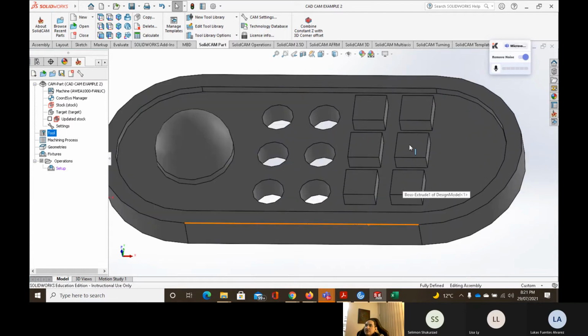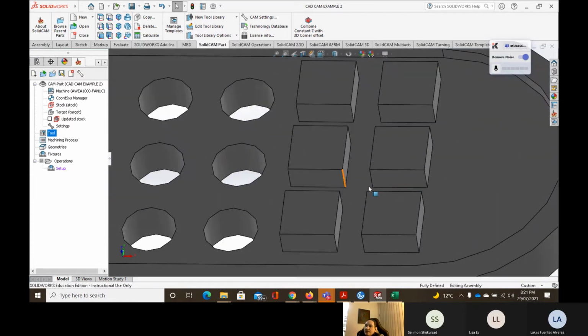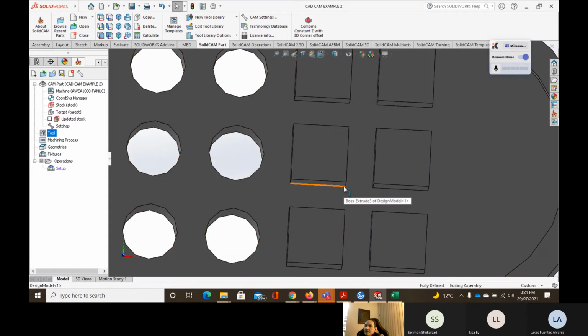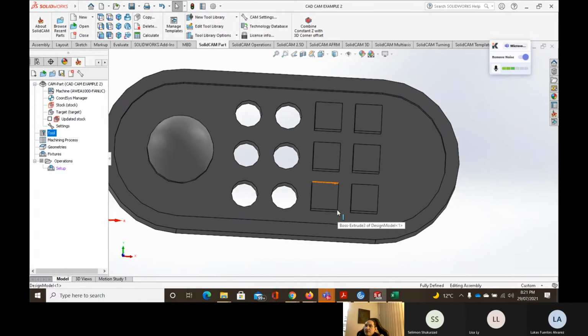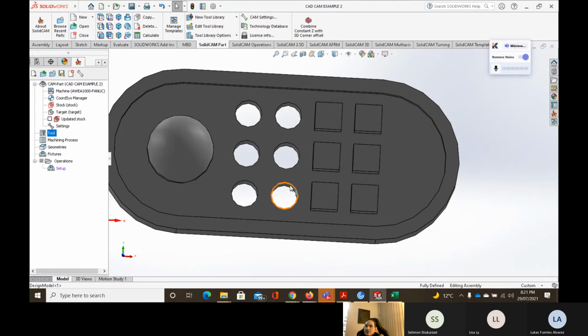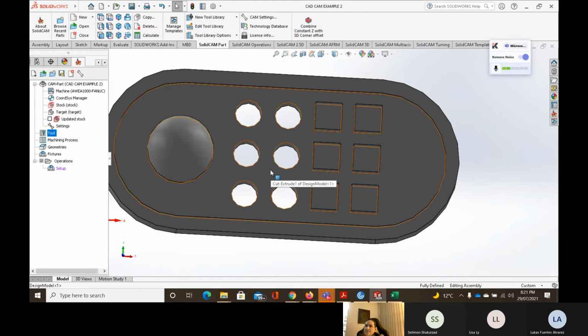To select the tools, we need to pass the tool form here between these cubes. The distance from this line to that line is 10 millimeters. I'm going to choose the cutting tool to be an 8 flathead. I'm going to do drilling for these holes, 20 millimeters. I'm going to choose a cutting tool of 20. I thought this would be too much. Anyway, 20 to do the drilling for these holes. I just want to increase the number of the tools.